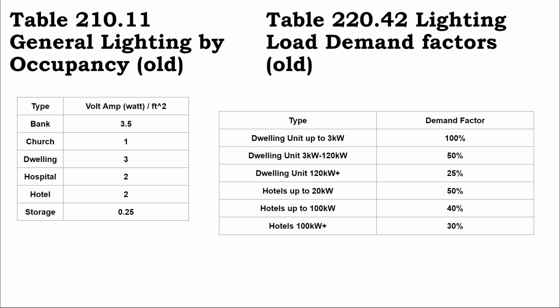And so here we have some general lighting load calculations. We kind of talked about this in the changes. But basically, if I'm designing a home and I want to start estimating what its energy usage is, I actually don't do it this way. I go find electric bills of similarly sized buildings and kind of go into it that way. But there are general assumptions being made at how much power per square foot particular electric loads need to be sized for.